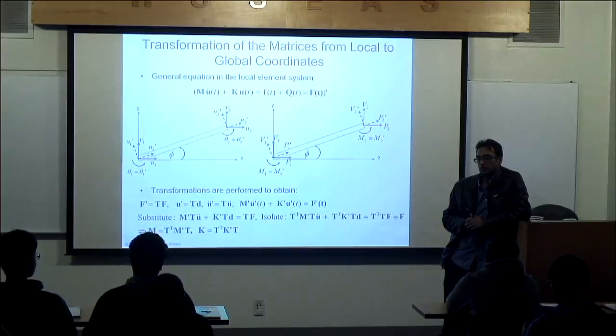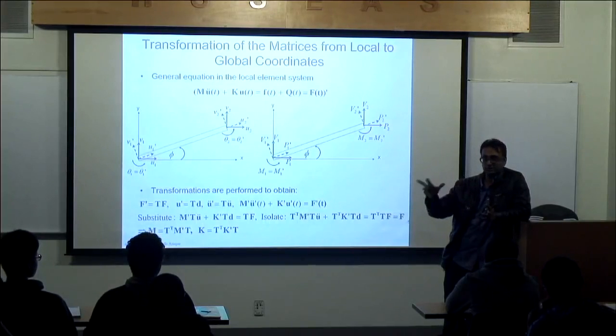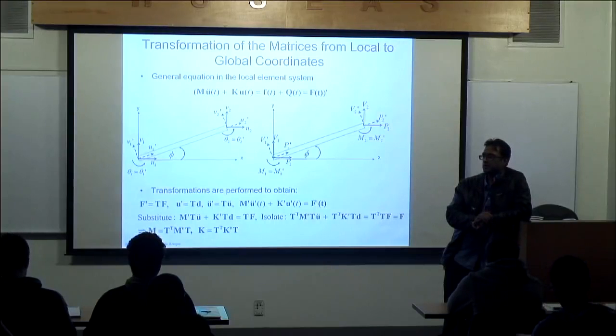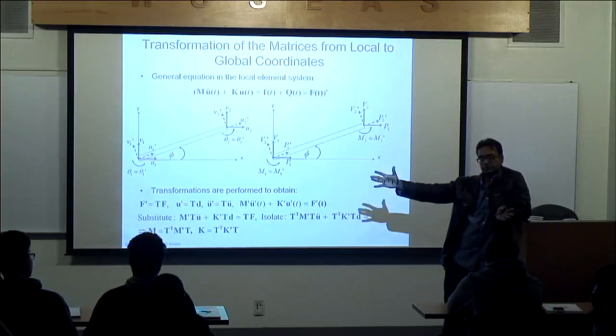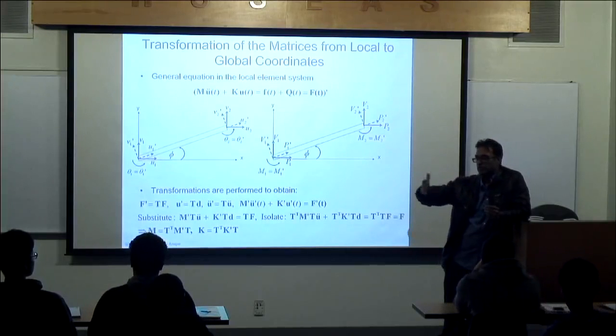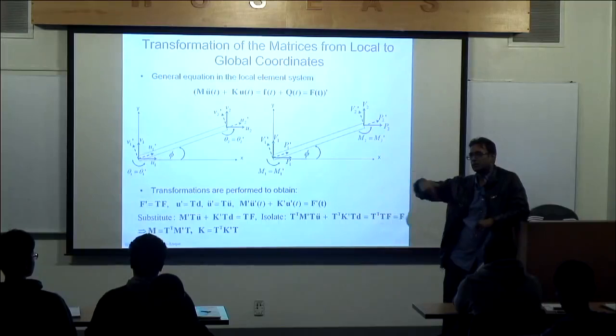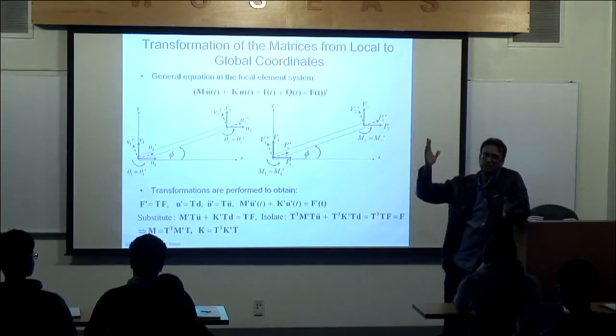Because what I can do is calculate, you know what mode shapes are? Anybody knows what mode shapes are? You can calculate the modes of the system, and I can just maybe calculate 15 modes of the system. And these 15 modes, if I take each mode and multiply by an amplification factor, a linear combination of these modes are added together, and I say that the response of the system depends on these 15 modes. And I don't care about any of the other modes because they're not relevant.